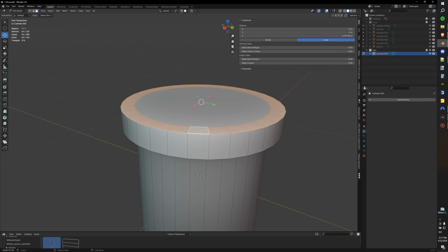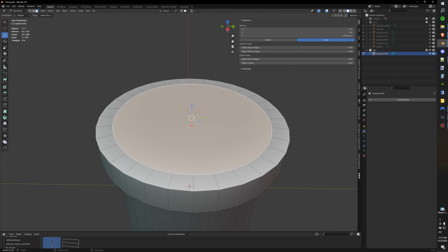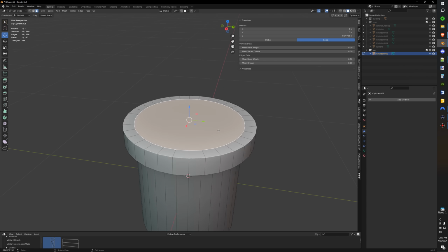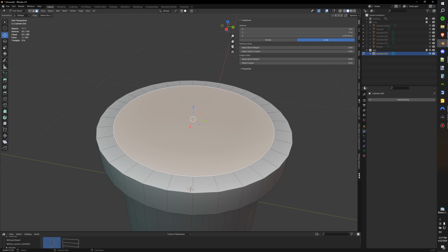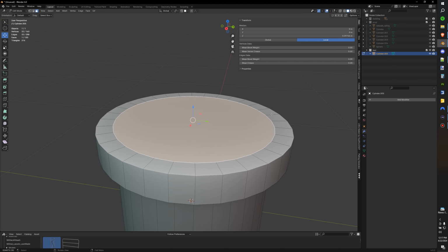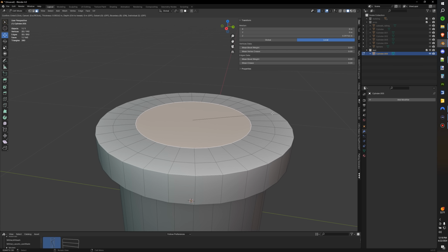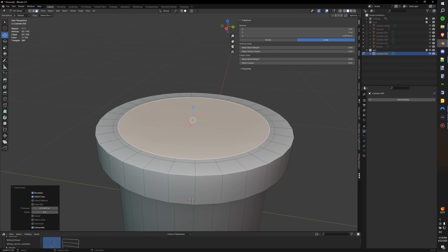But now we have kind of a lip on there, right? And let's say, I don't know what it is we're making. Let's make a Super Mario tunnel. So the next thing with this top face selected, we're going to press I. And I is going to do kind of the same as extrude, but a little bit different. It's actually going to create a whole new set of faces here that we can scroll in and out. And we're just going to go right to the edge of this.